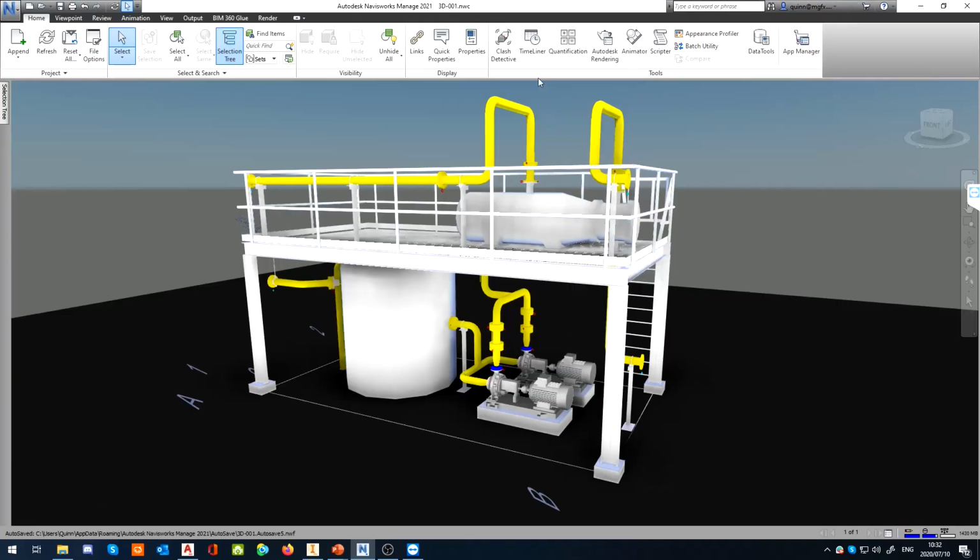That being said, you've noticed that I was talking about the NWC over there. Now this NWC is a bit of an interesting thing. It is a cached file, so it's referencing the original model. You'll notice that there are actually several different formats, most notably NWC, NWF, and NWD. NWF is basically a whole bunch of Navisworks files combined into one unit. So this is what the whole append and merge thing is about, so you can create a collaboration of all of your models together.